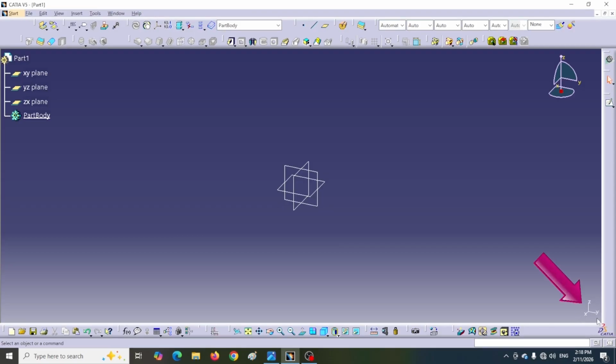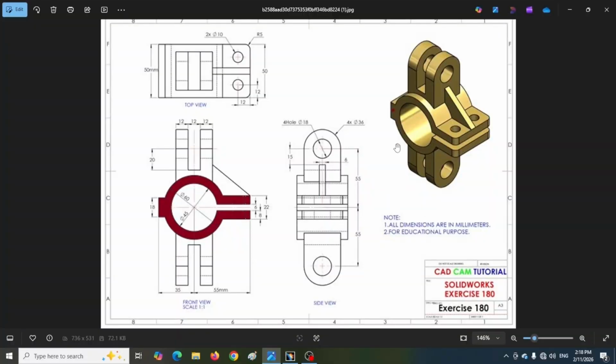Now look at my part plane and main coordinate axis. You can see the direction of the x-axis. I will place the tube axis along the x-axis. This way my 3D design will look like the shape. I can draw the tube first, then add the two straps. Or I can draw all three together and give them a pad. I will choose the second method.